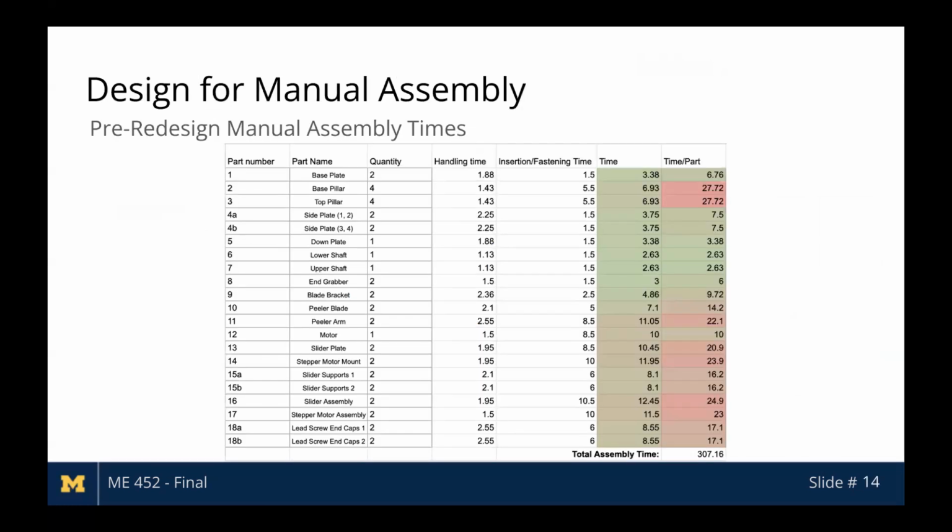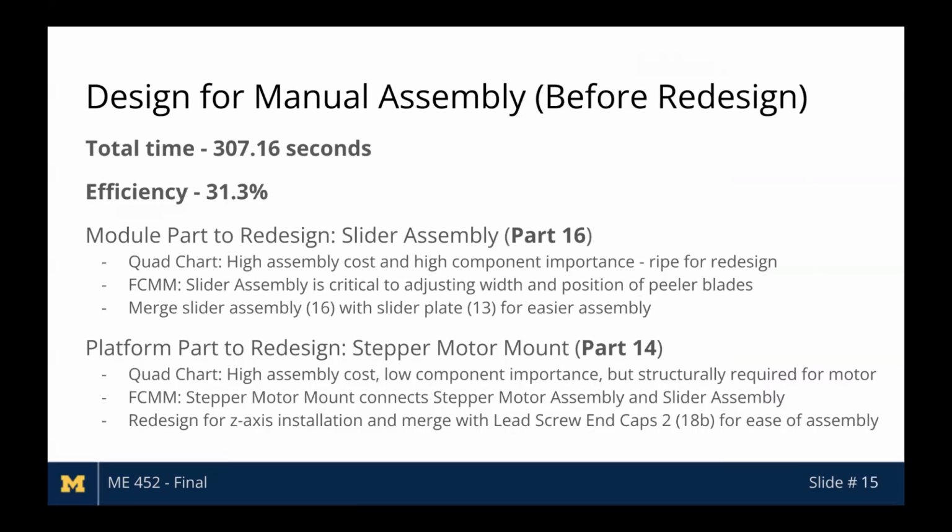Here's our manual assembly time chart. And we have very large assembly times for the parts associated with the slider assembly and stepper motor assembly. So to target this, we have chosen the slider assembly to redesign as the module part and the stepper motor mount to redesign as the platform part due to their high assembly cost, high product importance, and their critical functions on the FCMM.